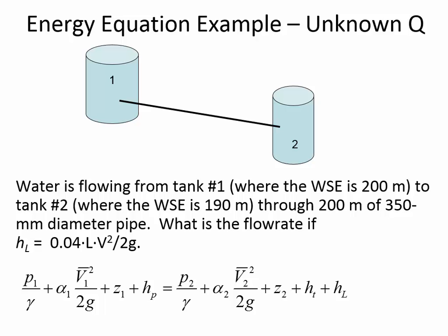Now the pipe, we have the diameter of the pipe, and we are given a special equation that's relating velocity to head loss. Now, you'll notice if you look on the equation sheet that I've given you for the exams, that there's a formula on there that says h_f equals f L V squared divided by D 2g. This is called the Darcy-Weisbach equation. And we'll spend almost the first 2 weeks of hydraulic engineering talking about this equation. In this example, we're simplifying things a little bit, and so we're saying all of the energy loss in the system, including the local losses and the friction losses,